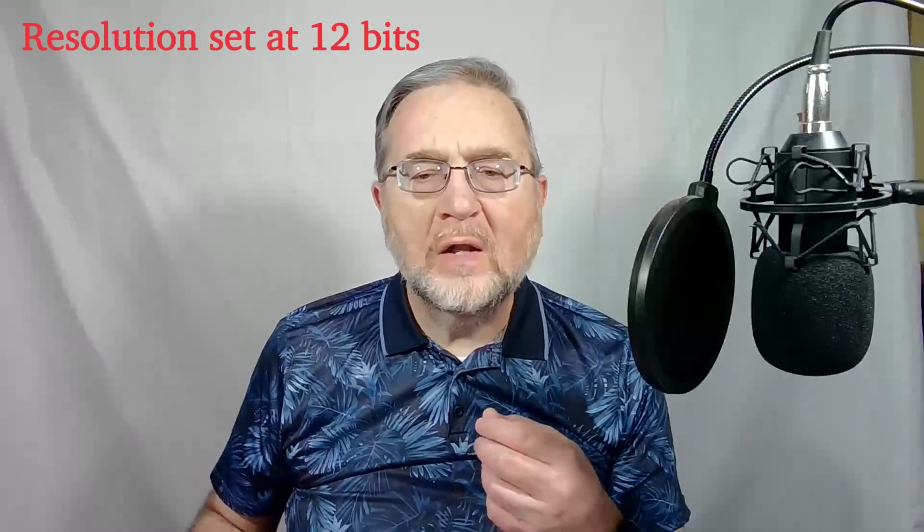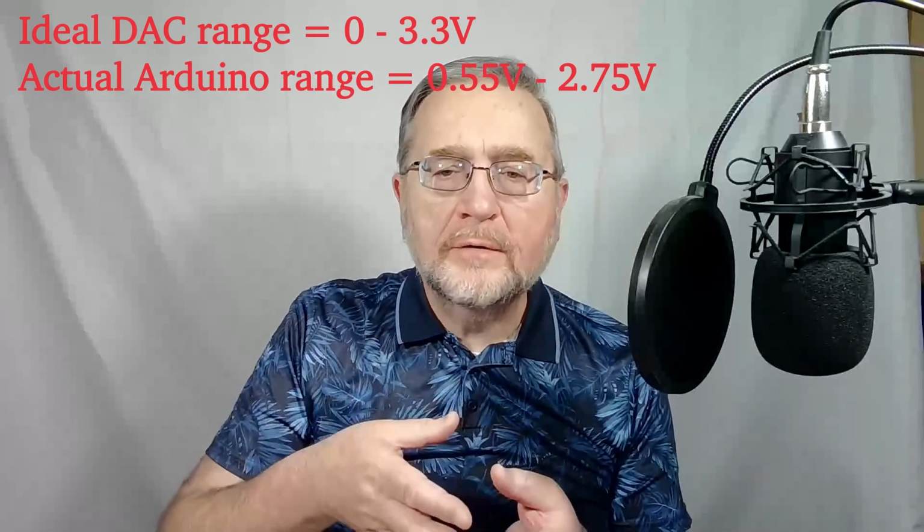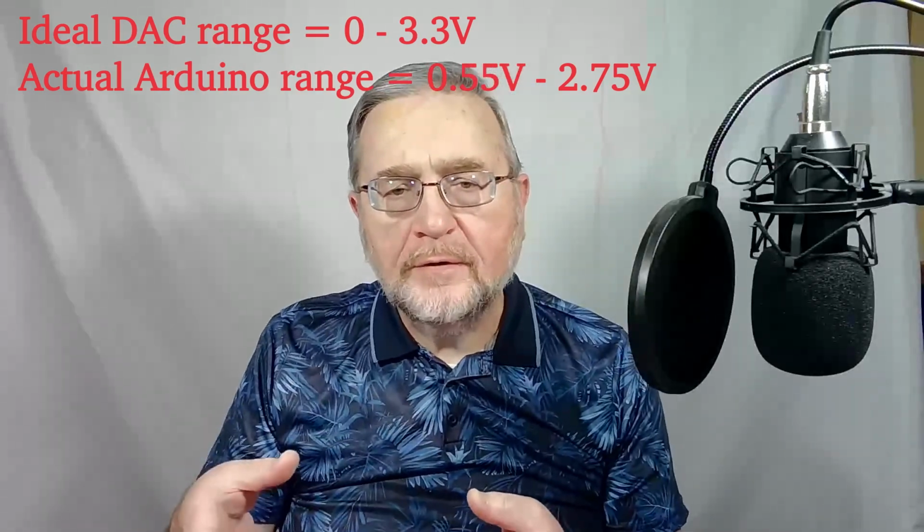Both DACs can work at several resolutions, which we can set with a simple function call. Given the kind of output we expect, we will set the resolution to the max value, which is 12 bits. Second, a regular DAC is supposed to output from 0 volt to its max value that is dictated by the logic levels used. But it's not so for the Arduino Due. Instead of having a range that should be from 0 volt to 3.3 volt, the DACs on the Arduino Due have a range that goes from 0.55 volt to 2.75 volt.